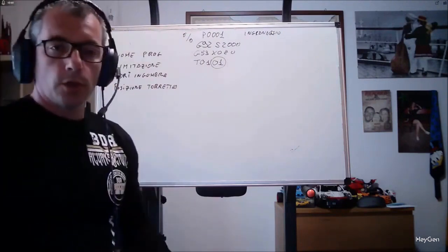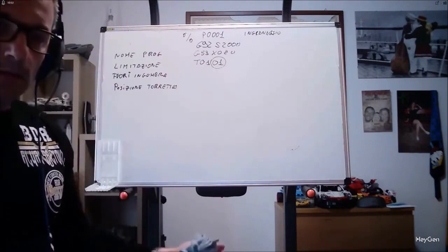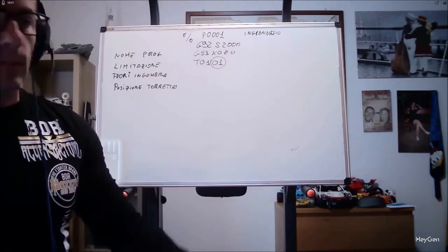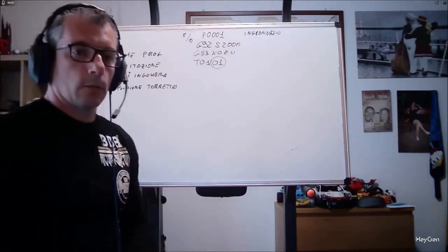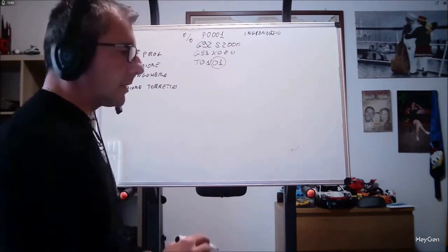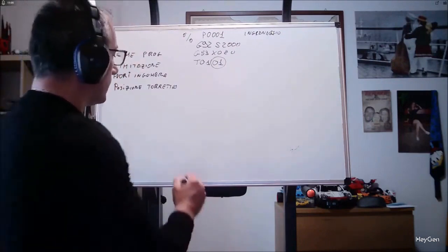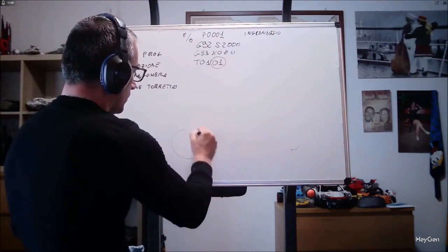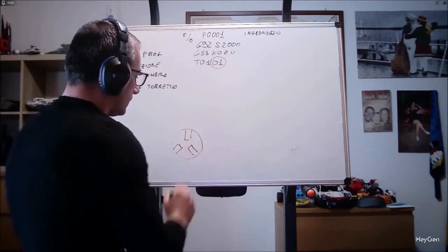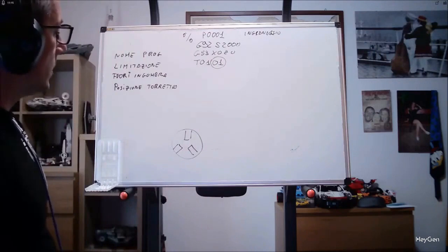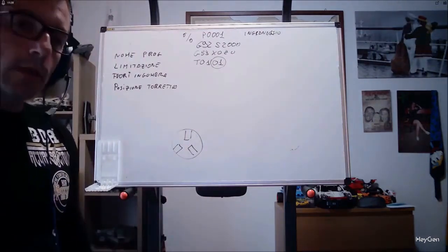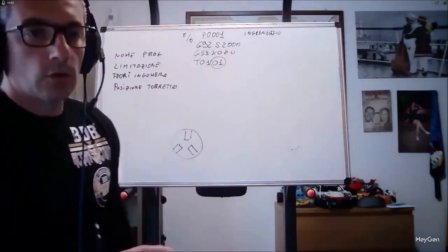Another thing at this point, the spindle will need to be rotated, and therefore the self-centering chuck and the piece on which it is mounted. So, to rotate the self-centering chuck, a series of codes must be given. Let's look at the self-centering chuck from the front. So, first code, if the machine has it, not all of them do. Normally the larger ones do, the smaller ones usually do not.